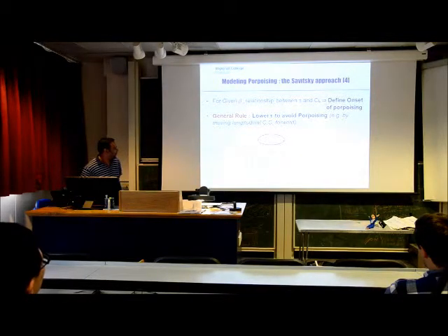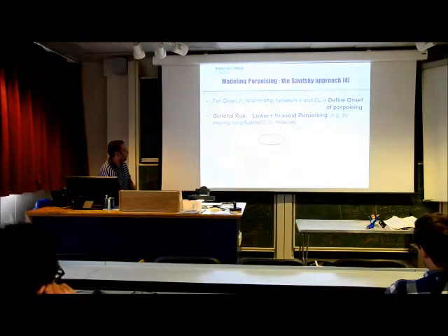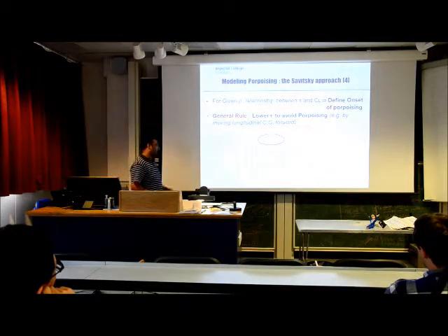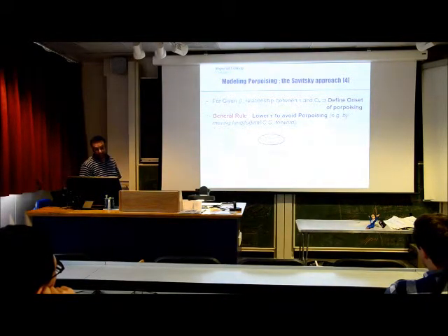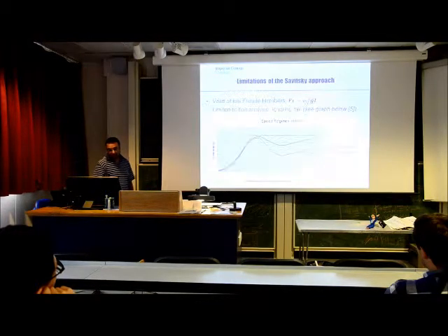And on this graph we can also see how trim angle varies with the lift coefficient, and how by defining a dead rise angle for our hull, we can define a regime of porpoising and therefore determine what our stability limits are with respect to porpoising.